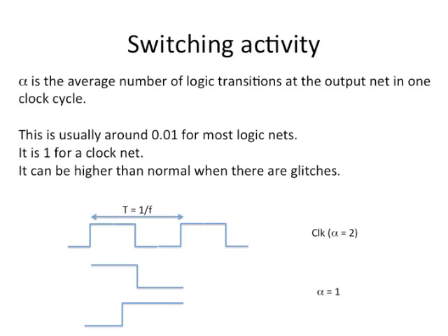Whereas you could have other bit patterns where maybe just a few bits in the LSB are switching. So alpha is really a very data dependent number. The same activity, the same computation, but different data patterns could lead to different alpha values.